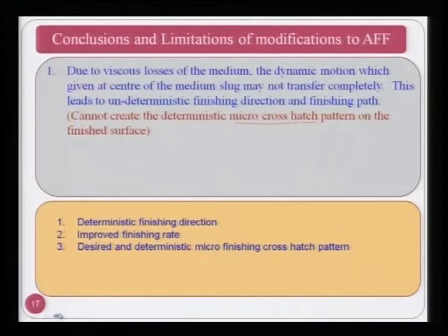Deterministic finishing direction, improved finishing rate, desired and deterministic micro finishing cross hatch pattern. These are some of the things which we are attempting to achieve, and for this purpose an attempt was made at IIT Kanpur, and that process was named the rotational abrasive flow finishing process. I will discuss this rotational abrasive flow finishing process and some experimental study.